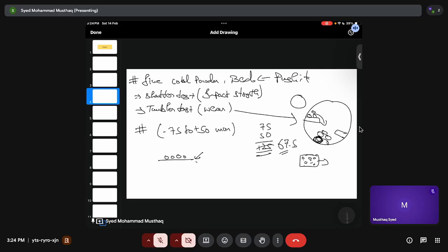Whatever the particles that remain in your 40 mm screen, you take them. Then that is called the MICUM 40 or M40 index.